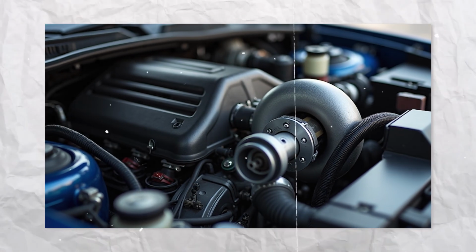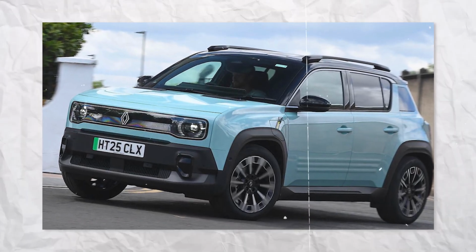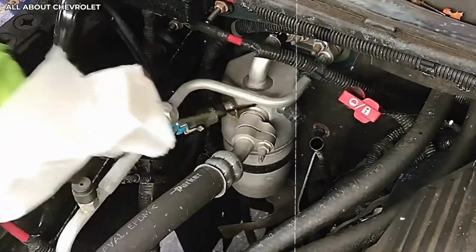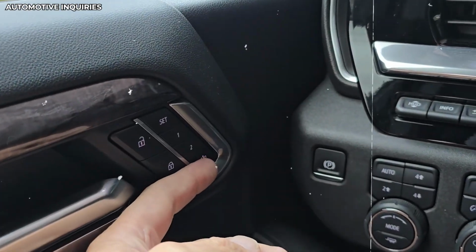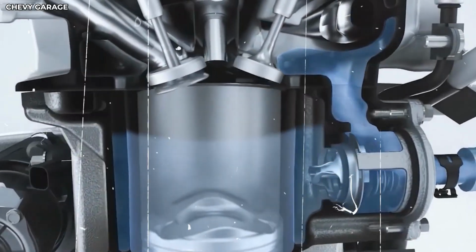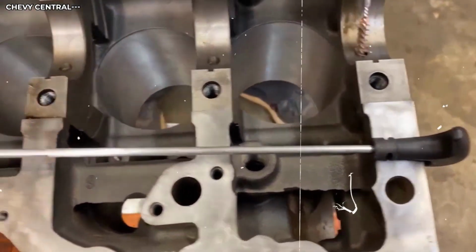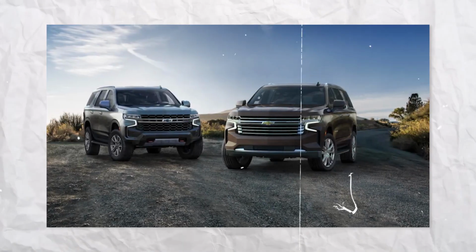Combine the adaptive learning reset with cleaning your mass airflow sensor and replacing your air filter. A clean MAF sensor provides accurate airflow data to the computer. When you reset adaptive learning with a clean sensor and fresh filter, the computer learns optimal fuel and throttle calibration based on accurate sensor readings instead of compensating for dirty components. For EcoBoost engines, consider installing a high-flow drop-in air filter at the same time you reset adaptive learning. The increased airflow potential, combined with aggressive adaptive learning, creates a noticeable improvement in turbo response and power delivery.